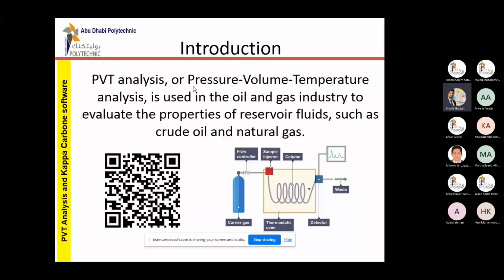So as a petroleum engineer, as a field development engineer, as an economist, as the person in charge of the whole company, the most important thing after discovering the reservoir is to know its bubble point. Because if we can maintain the reservoir above the bubble point, it is beneficial for us. That's why we do the PVT analysis. This is the main thing.